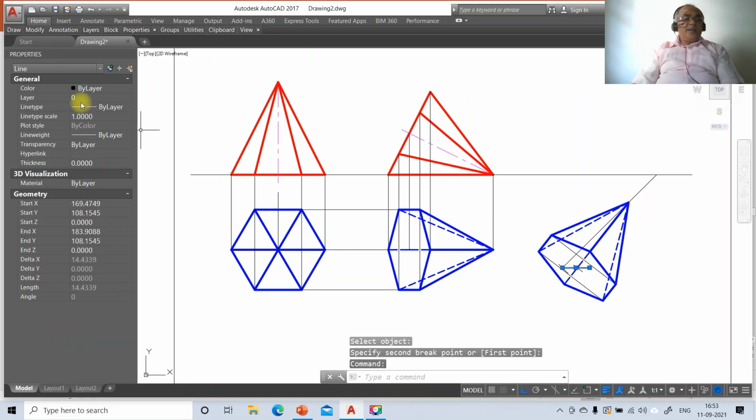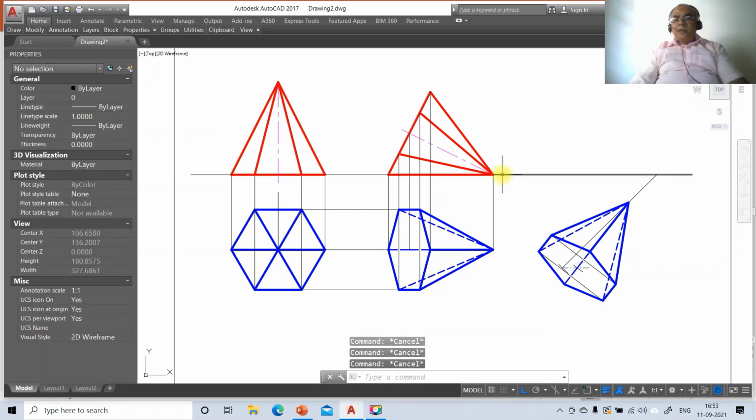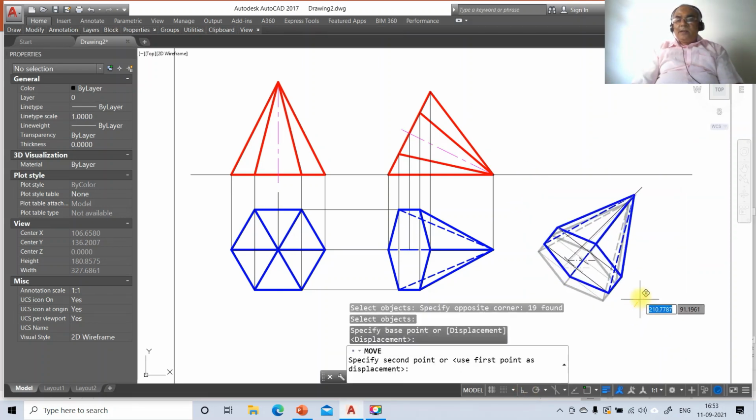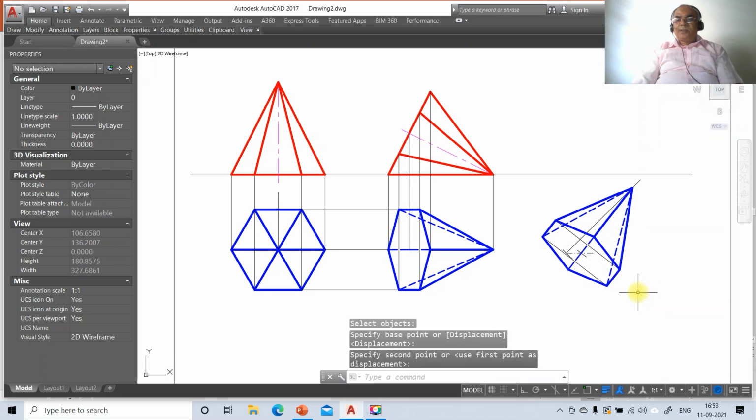Now you just select this line, go to layer, make that layer as locus layer and mark this as 5 mm. So once you do that, we have break this line till here, then you switch off this, then go to move, select this and move this appropriately and keep it.